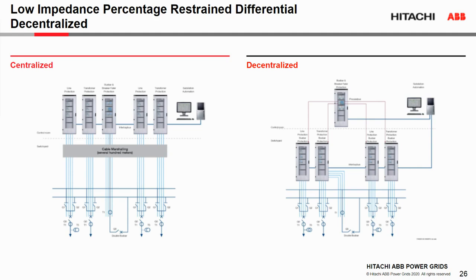However, the limitation is the number of inputs each individual relay can support for those analog inputs, those CT circuits. There's a set limit there, restricted by the hardware. Some vendors have more, some vendors have less. Regardless of how many you have, let's just give a number: for three-phase, the most on the market is probably 10 or 12. That's already a lot. If you have 20 feeders you want to protect, I think the only way is to go with this decentralized scheme.